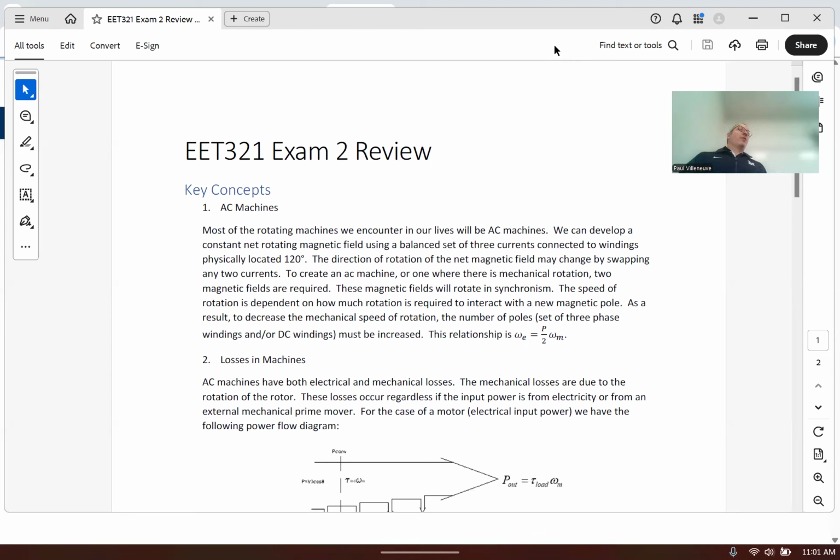But again, the square root of three is usually just for phasors. Otherwise than that, it's just a value of three. So voltages and currents are line and phase quantities. Everything else is either a single phase representation or an accumulation of all three phases. So power is three times a single phase. Voltage and currents are either square root of three or no square root of three, going back and forth.